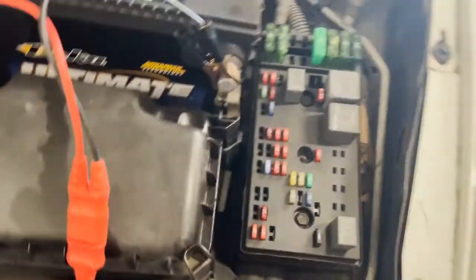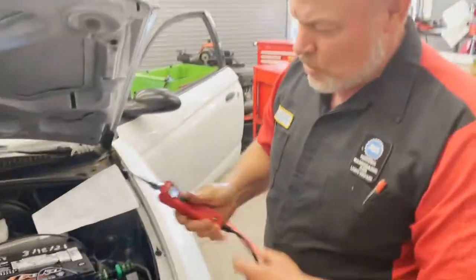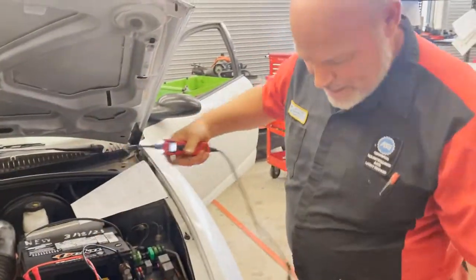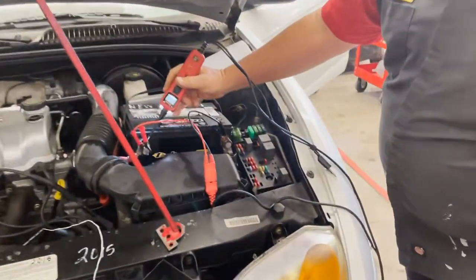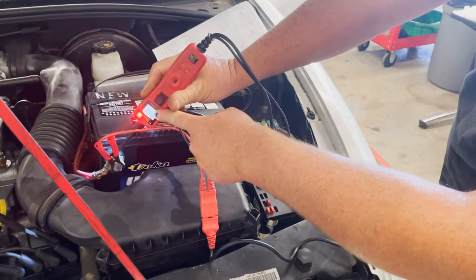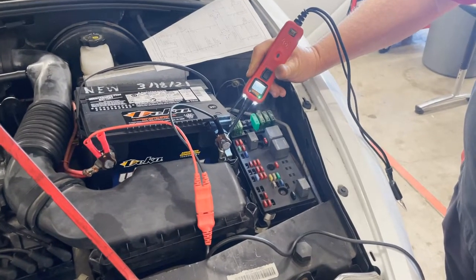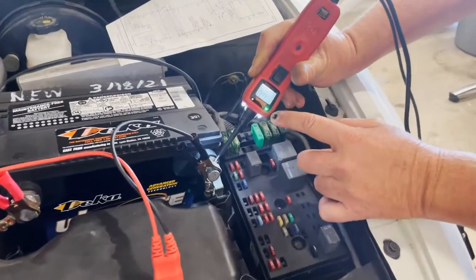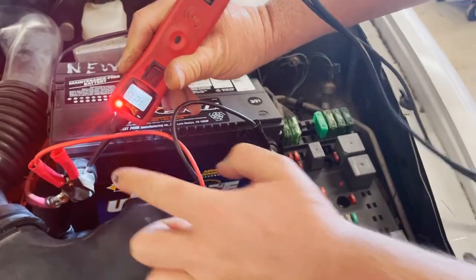For our circuit today, we're going to use what we call a power probe. A power probe, you hook it straight up to the battery. It has a huge pigtail. It has audible sound, so if I touch power, it tells me if I have power and gives me a voltmeter. It's 12.6, so I have a full battery. And then it'll tell me if I have ground with the sound. Plus, it gives us a symbol, ground, positive.